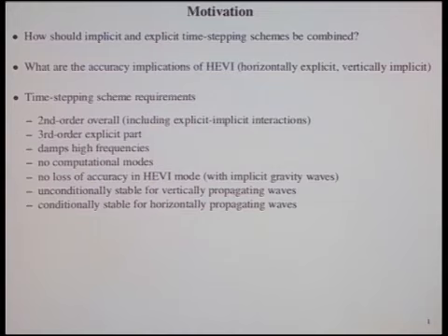Sure. Implicit is not inaccurate because it's implicit. It's because it's a long time step. With the same time step, it's much more accurate than explicit. Yes, yeah. But it's because you might have a CFL of 100 for an acoustic wave.